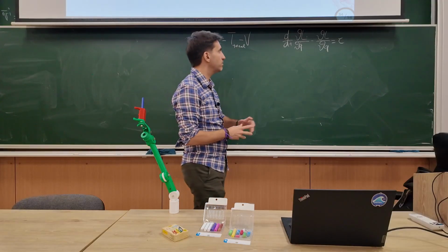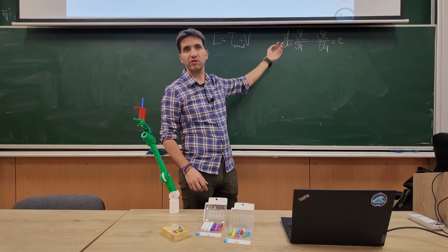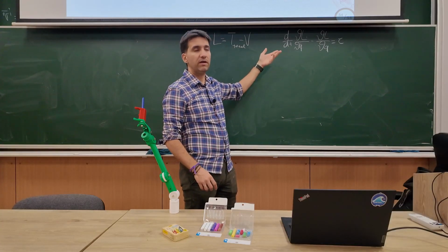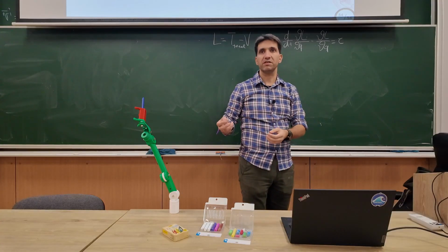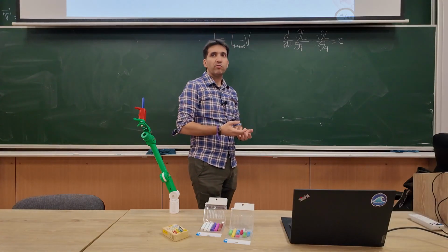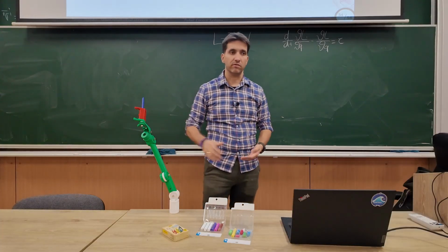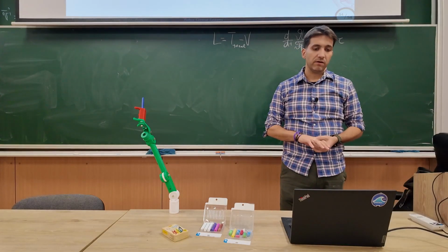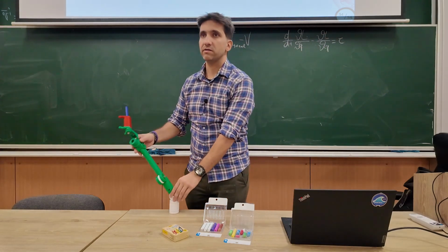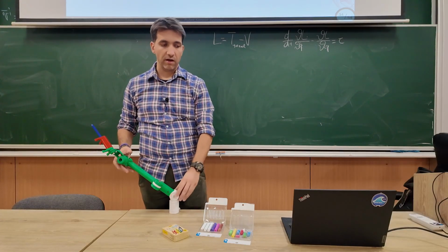I'll explain because it's maybe too far-fetched, but you saw when I did the derivation, basically I put the inputs at those coordinates, at those degrees of freedom. I want to have equations of motion where the inputs are at my joints, so basically joint torques for revolute joints or joint forces for prismatic. And I want to have an output of joint accelerations, which I can then use to calculate forward kinematics, velocities, and so on. In the end, the state of my robot can be fully described by the joint coordinates, by how the angles are rotated or translated, and how fast they're moving.